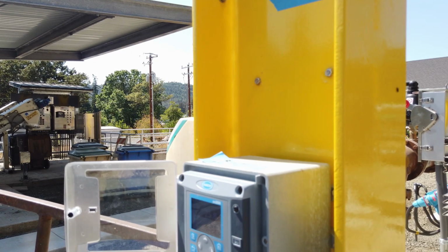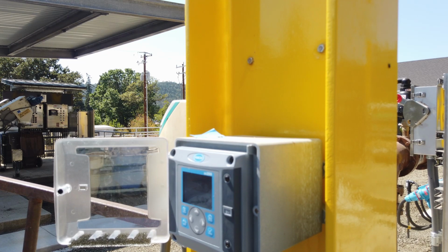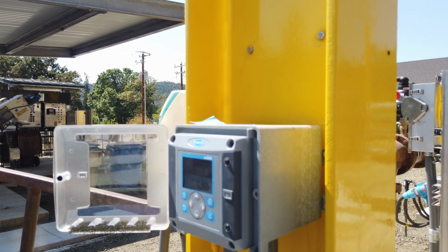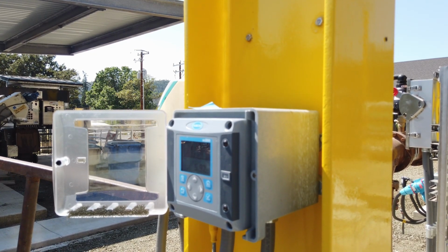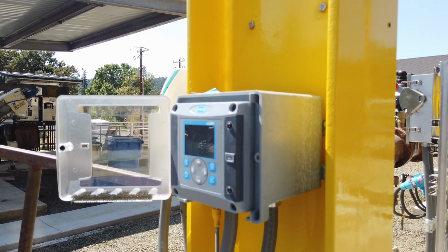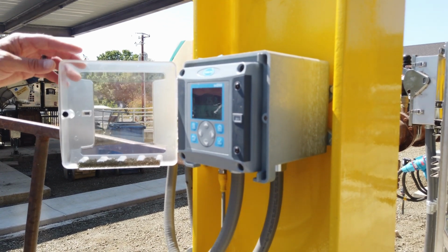Also in the RAS-WAS tank is a pH probe. This provides a 4 to 20 milliamp input to the main MBR PLC to facilitate alkalinity feed rates based upon the instantaneous pH value. If the pH drops, feed rates are increased automatically.